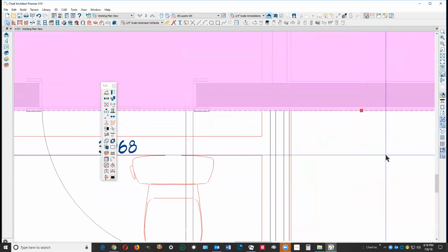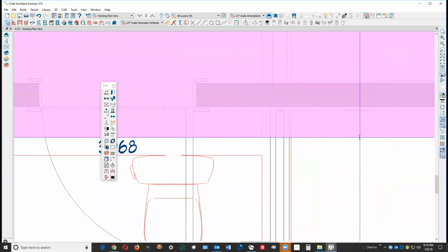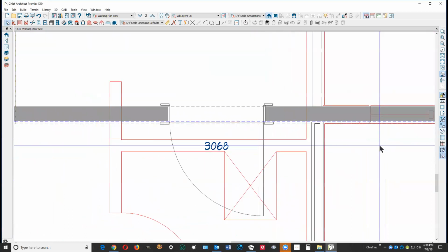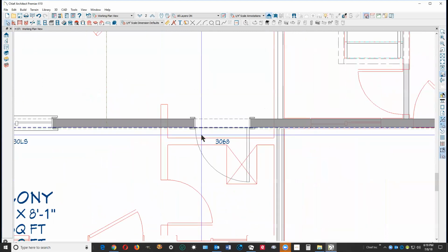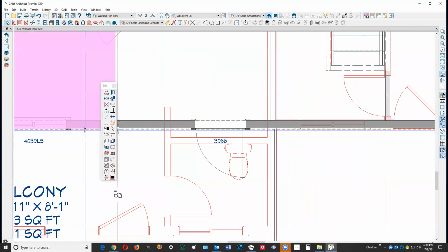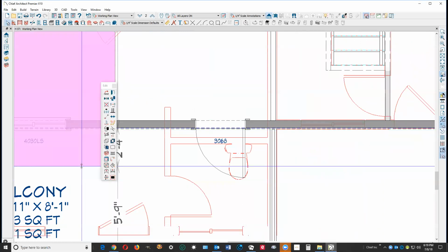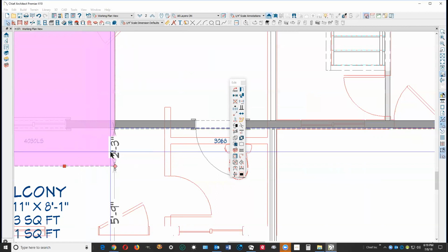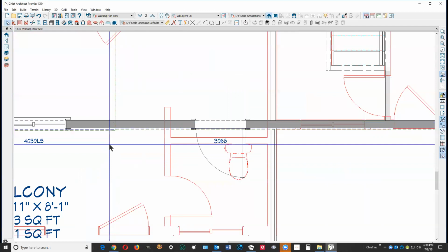You know, having zero overhang is probably not a very good idea. I'm going to jerk it out there and make it an inch. Zero overhang just doesn't work very well in cheap architect software, in my experience. You need some overhang so that the roof planes can do the job that they're supposed to do by cutting off the wall below. So I'm just going to drag that roof plane out, move the edit toolbar out of the way and set that to 1 inch. I don't know that that's going to make any huge difference.